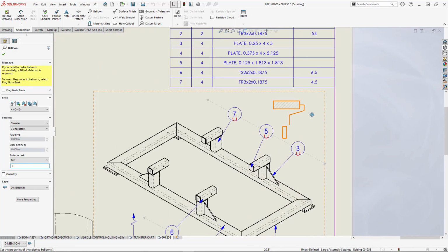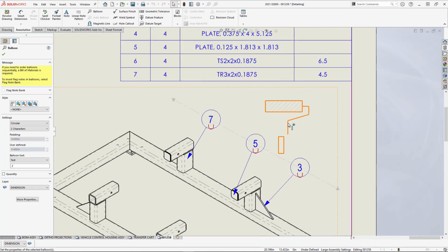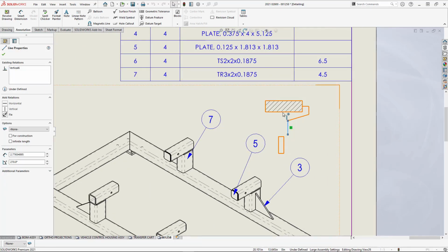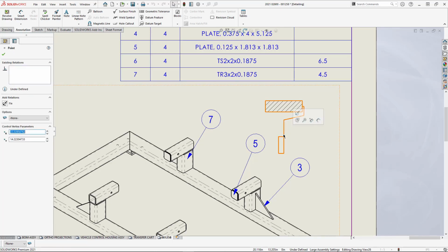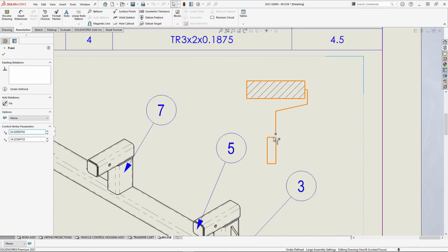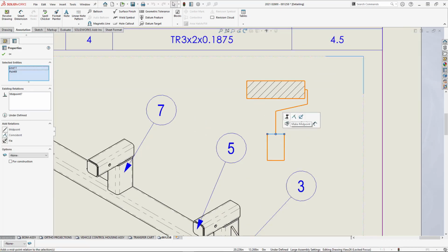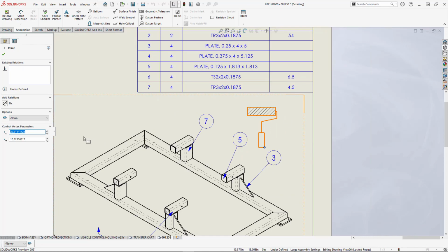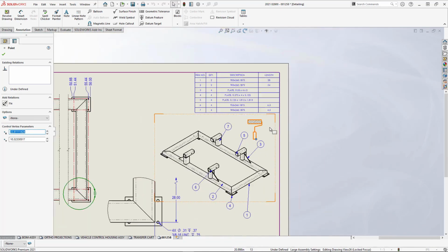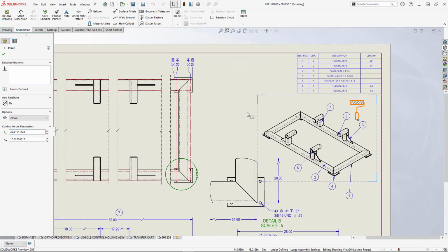Last thing I want to show you is some sketch enhancements. Now when you're dealing with sketches, you can select, of course, multiple entities, and the shortcut bar is going to pop up where you usually expect it in sketch mode. So I'm going to go ahead and make these guys coincident. We can select on lines and points, make them midpoint, and kind of drag them around where I want. So kind of keeps you from having to go all the way over to the dialog and then all the way back. We can now do that right in place.